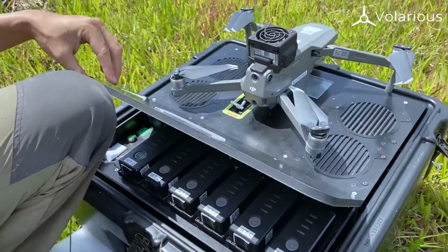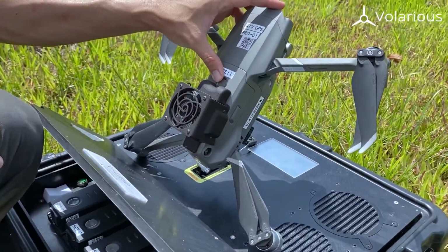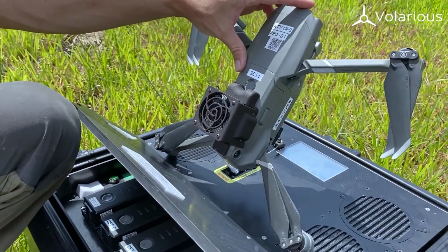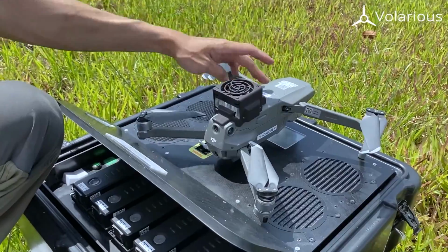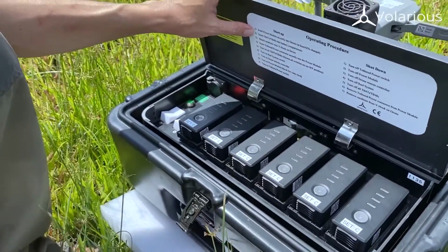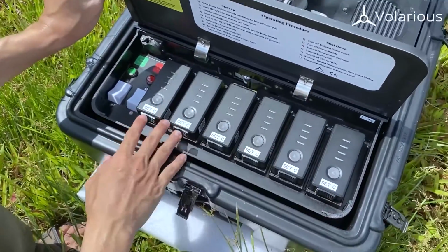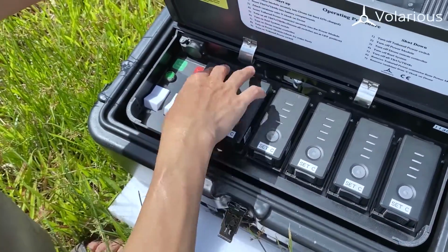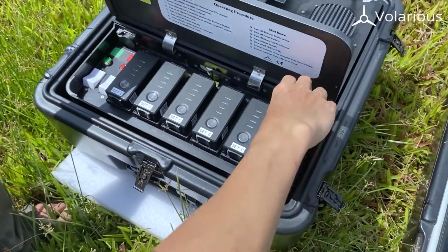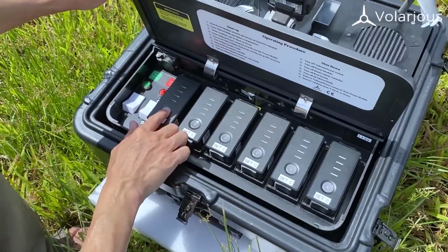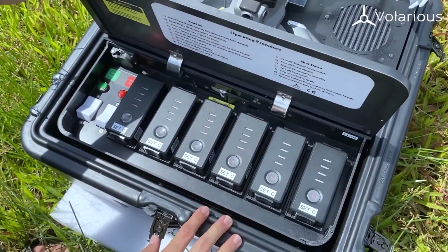First, we need to ensure that the backup power module is inserted onto the drone. You notice that this backup power module is slightly different from your standard Mavic 2 battery. So the drone battery is connected onto the drone. Step 1 done. Step 2, inside the V-Line, we have 6 of these TB47 or 48 batteries for the Matrice 600. All these are standalone individual batteries to use in one set together with this V-Line. So all 6, let me just double check the power level is fully charged and ready to go.